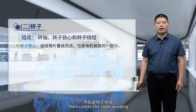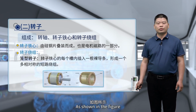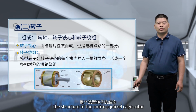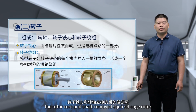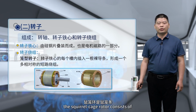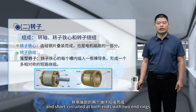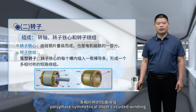Then comes the rotor winding. Let's first introduce the squirrel cage rotor. As shown in the figure, the left side illustrates the structure of the entire squirrel cage rotor. The figure on the right shows the rotor core and shaft-removed squirrel cage rotor. We can see that the squirrel cage rotor consists of rotor bars inserted into the slots of the rotor core and short-circuited at both ends with two end rings. This forms a polyphase symmetrical short-circuited winding.